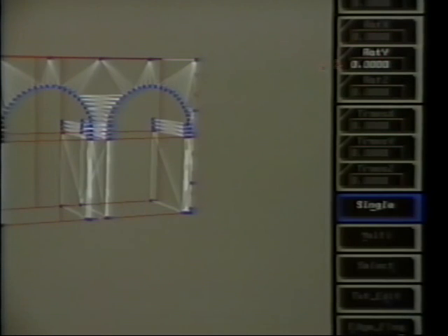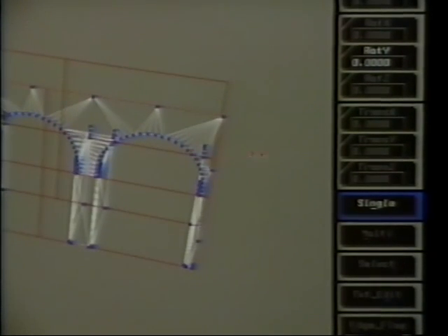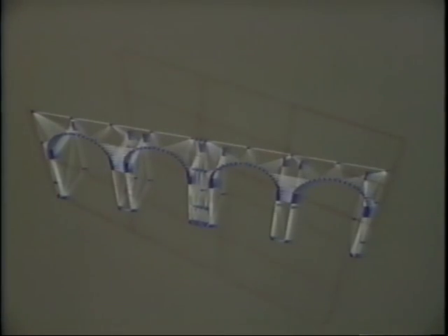If we preview the object, we'll see that the front looks pretty good, but the texture is stretching out along the parts of the object that run back with the angle of projection. There are different ways to solve this problem. One is, while we're in texture mode, simply rotate the texture in Y so that it's off-axis from the walls. This works pretty well in this case, but sometimes takes away control over the specific mapping for each wall.